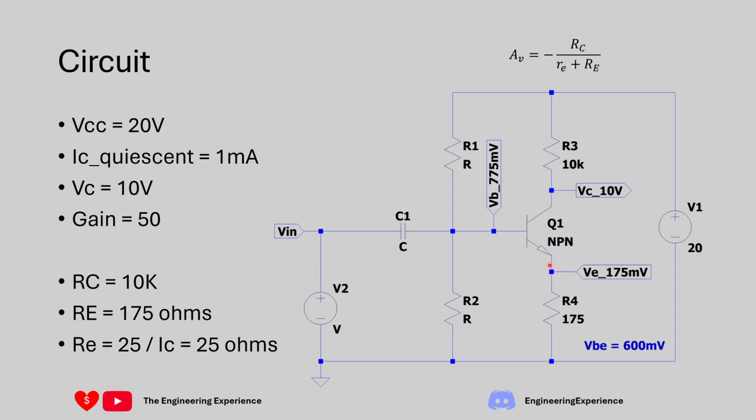Now for case 2, the only thing that's happening is that the VBE voltage is decreasing by 2.1 times 20 degrees. So 20 degrees is the temperature change, and the base emitter voltage decreases by 2.1 millivolts per degree C. You get a larger voltage here because you get a smaller voltage drop across VBE, as this will stay fixed, or we're assuming that this will stay fixed. A larger voltage here means that we have more current flowing through this direction.